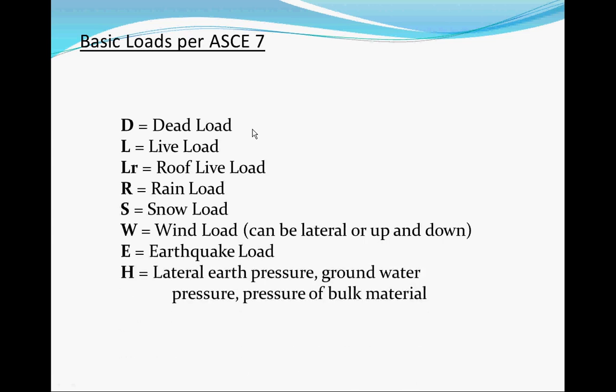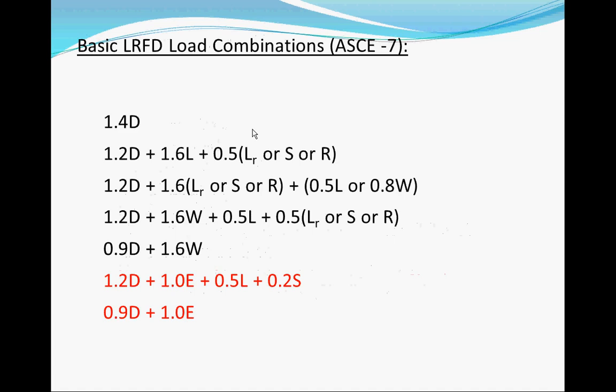Okay. There's also the lateral earth pressure and groundwater. We won't be covering these because they're just for foundation walls or other earth pressure on your structure. The frames are not going to be seeing this, so we won't be having this in our load combinations.